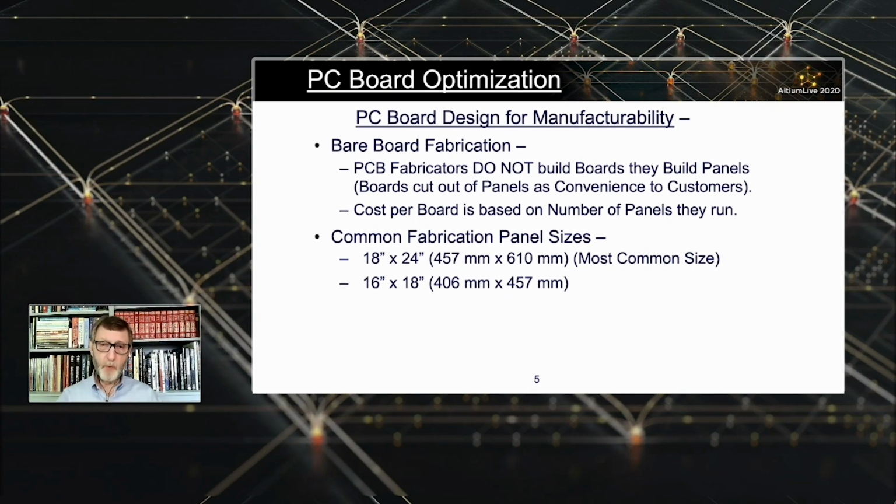Well, I'm going to show you in a minute why this is true, but that board size panelized terribly. I mean, terribly in everything that fabricators had that they could produce. The closest they could get to reasonable production with the 12 by 13.8 motherboard was in a 16 by 18 panel that we're talking about. Well, for the first few months to a year or so that the PC existed, everybody who bought them, whether it was IBM or the clone manufacturers making other versions of that same design, anybody who bought a motherboard paid too much because they didn't panelize well in these panels. And the majority of the material from the panel got tossed into the trash.